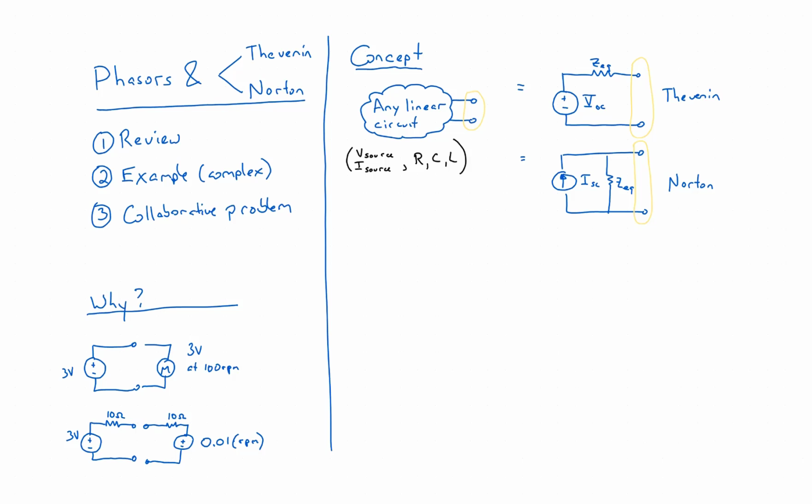It actually does, because you can run a motor as a generator. If you rotate the shaft of a motor, it generates a voltage. It's called back EMF. This particular motor generates a back EMF of 0.01 times whatever its RPM is. So if you want it to run at 100 RPM, it's going to generate a back EMF of 1 volt.